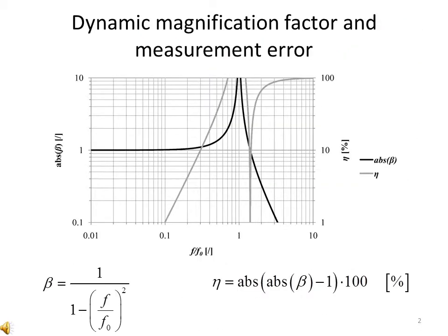When considering a common experimental setup with the test sample clamped at one end and attached to the linear guides at the other, its in-plane dynamics can be represented with a single degree of freedom system. The response due to magnetostriction depends on the scale of the excitation phenomenon, as well as on the dynamical coupling between the sample and the setup. The latter presents a disturbance to the measurement as it artificially scales the response.